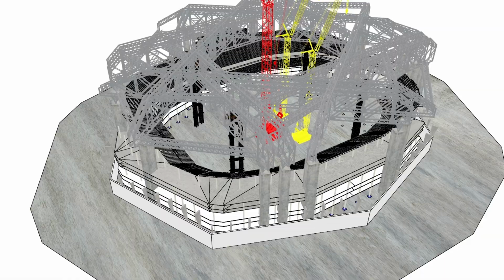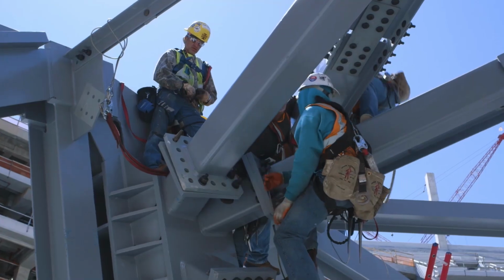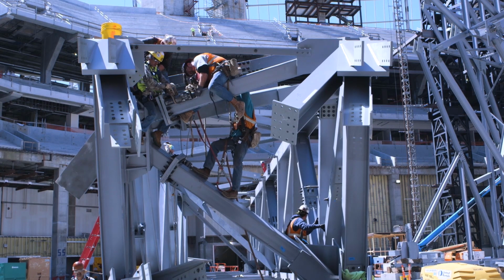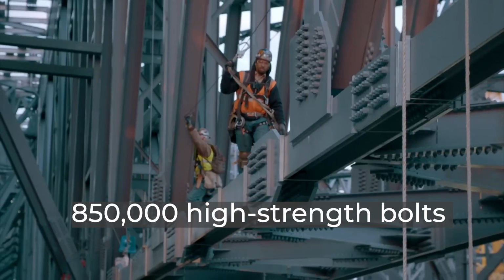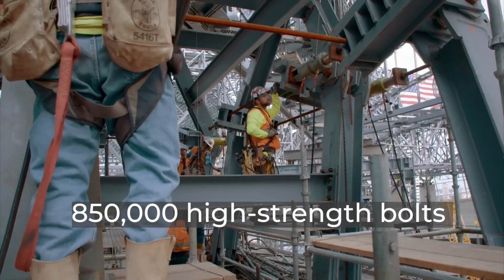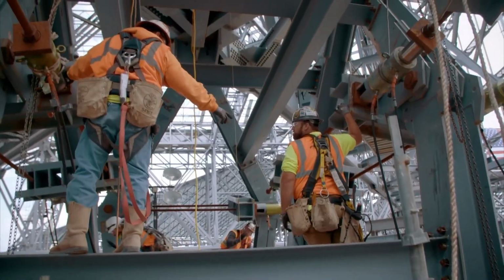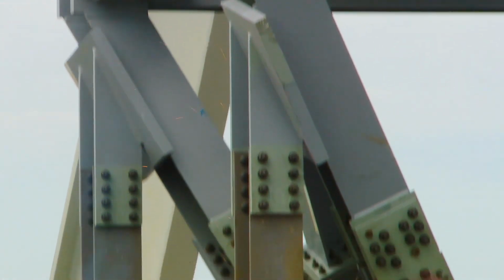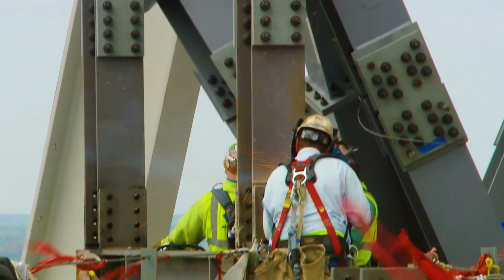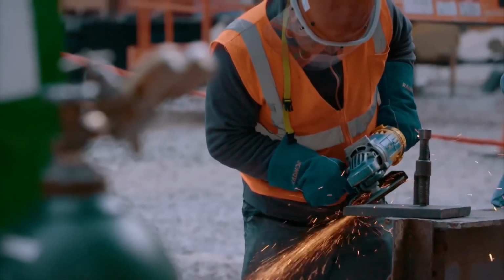The connections between trusses were executed with high precision using a combination of prefabricated high-strength bolted joints and on-site welding. In total, more than 850,000 high-strength bolts were used throughout the structure. For certain large connection points, field welding was employed to fully integrate the steel components, ensuring both connection rigidity and overall structural safety.